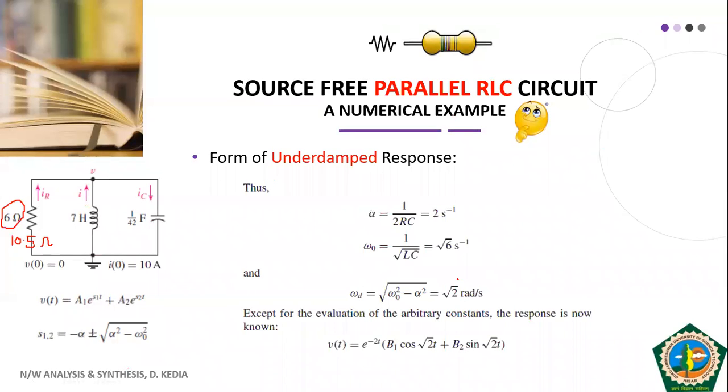So this is the circuit that we studied for the case of overdamped also. Now we have converted the same circuit to underdamped. Okay, and for that we need to change the value of alpha and omega naught, and in order to change them, we need to change the value of the circuit component. And here we have changed the value of R from 6 ohm to 10.5 ohm.